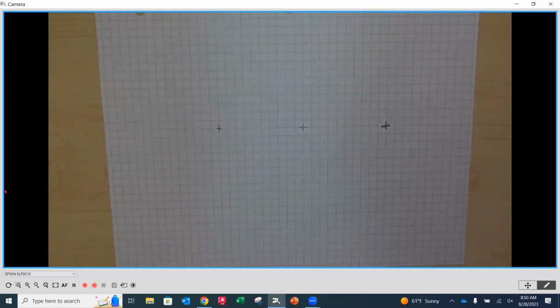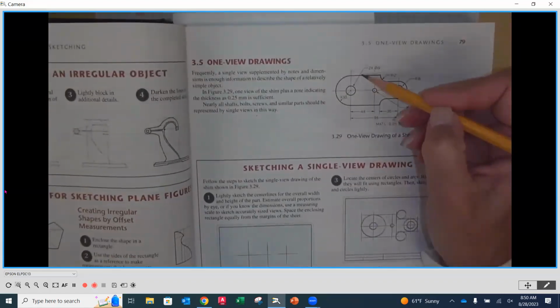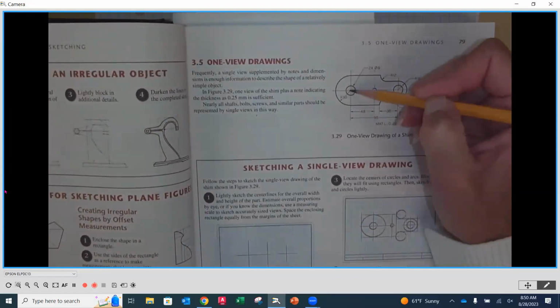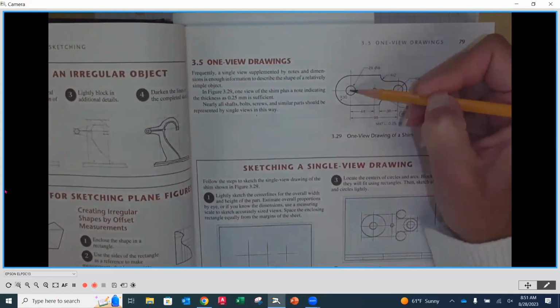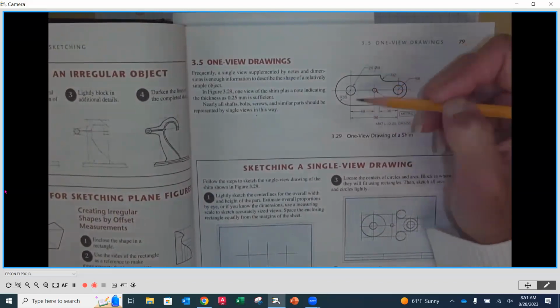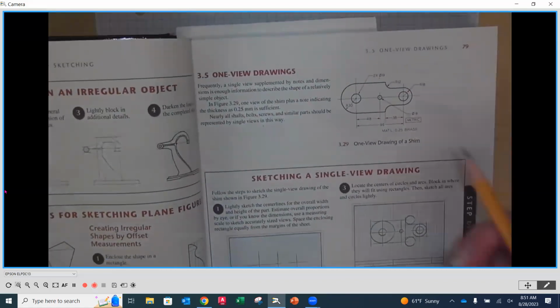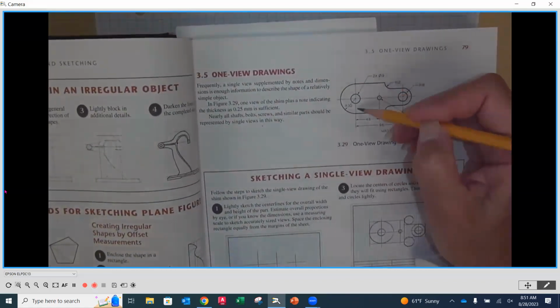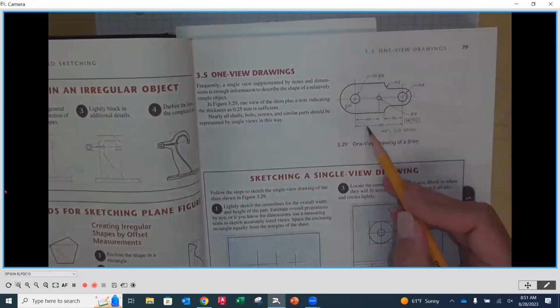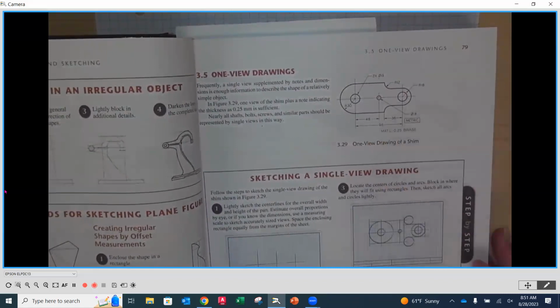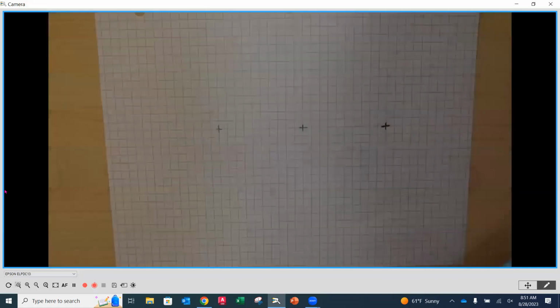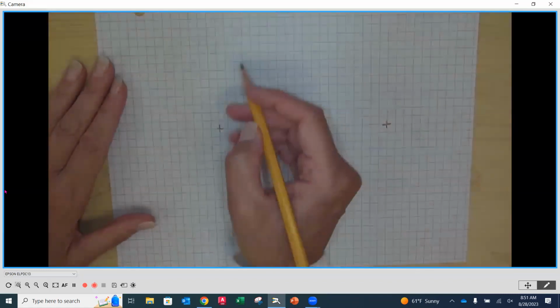So the height of this is a radius. If you'll notice, it doesn't give us a height dimension from top to bottom. It's dependent on this radius here. So that means it's going to be 30 above the center line, 30 below, 30 above, 30 below. And as we look at this proportion wise, 60 is going to be about 2/3 of 96, right? So proportionally, we want to put that in there.